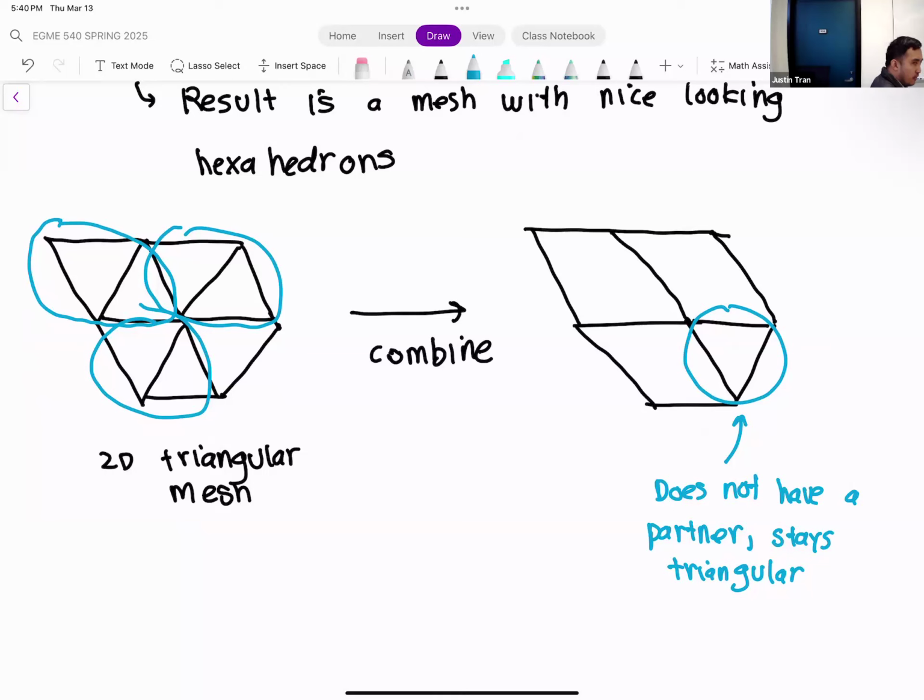Part of the difficulty of making a generic hexahedron mesh, at least when I was in grad school, is that you can take any geometry and put a bunch of points or nodes in there, separated by a certain distance. It's connecting those nodes in a way that creates a cohesive mesh that's different. With tetrahedrons it's a little more structured and easier, because there are fewer connections to make per node.